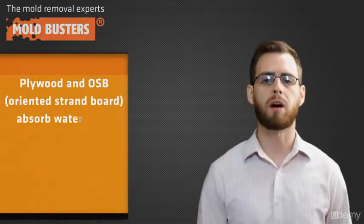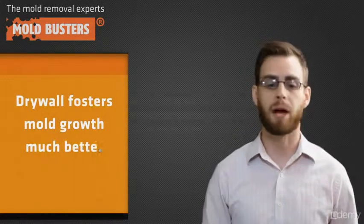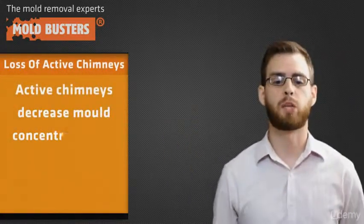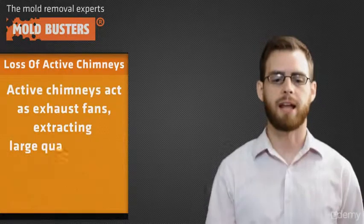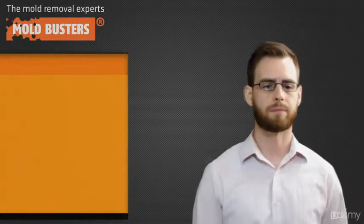Plywood and OSB, which is oriented strand board, absorb water up to 5 times faster than conventional lumber. Drywall fosters mold growth much better than plaster. And thermal insulation does not allow wall cavities to dry out after a water intrusion. Loss of active chimneys. Active chimneys decrease mold concentrations in the indoor breathable airspace. Active chimneys also act as exhaust fans, extracting large quantities of air from conditioned living spaces.